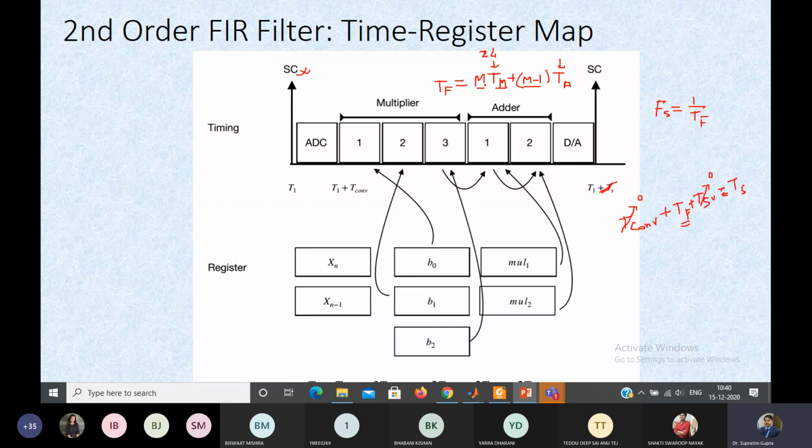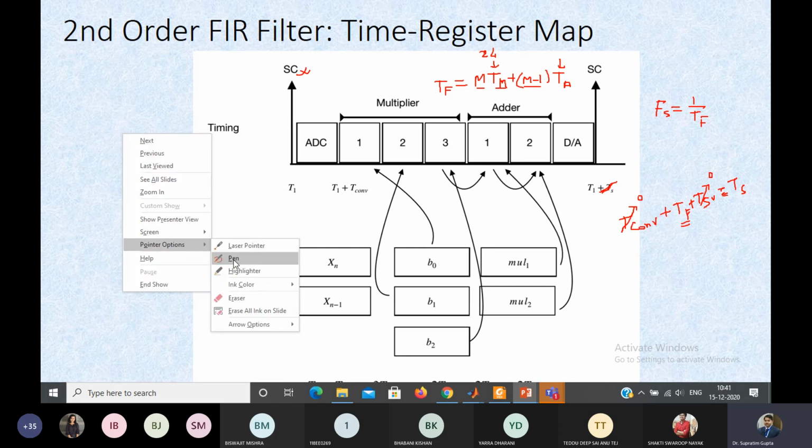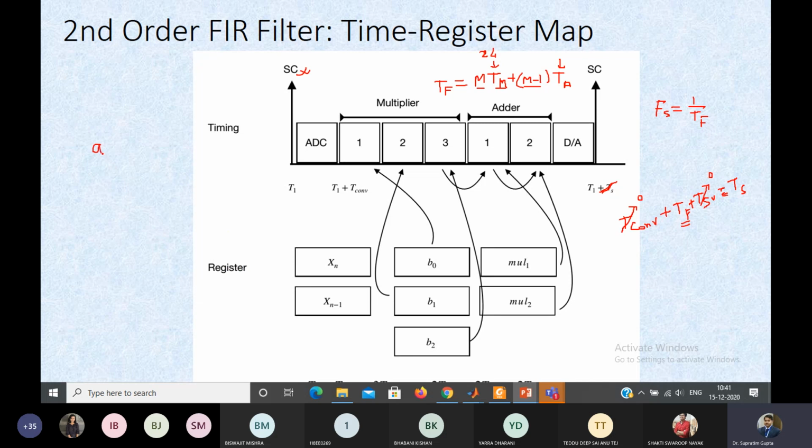we can represent the signals and the coefficients in fixed point format, and so whatever coefficient values we get from the MATLAB filter design tool, those are, say, fractional values, and now you want to convert them into, say, 0.8 format. So if you want to convert it into 0.8 format, what you have to do is the coefficient value, that ak, should be multiplied by 2 to the power 8.